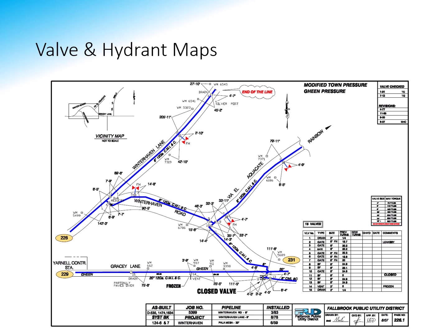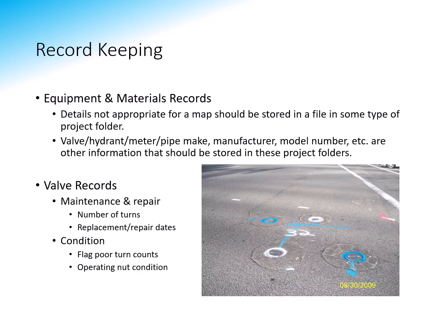So other information in here, you can see they're calling out closed valves. That's always good to know because you know those are two different pressure zones. You've got street names, and you can see it's calling out the type and size of the main. The water table here will give you more information on those mains. You've got a little vicinity map, so even though this is really zoomed in and you do have the street names, it's nice to have this vicinity map to give you that real basic information that helps you identify where you're working.